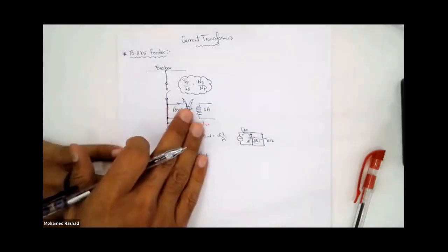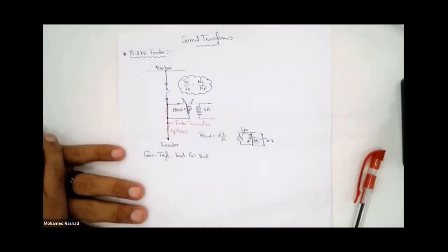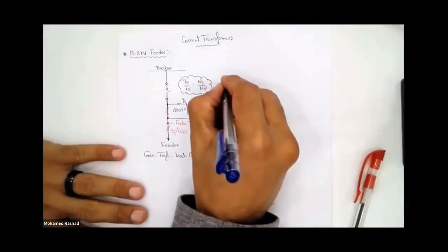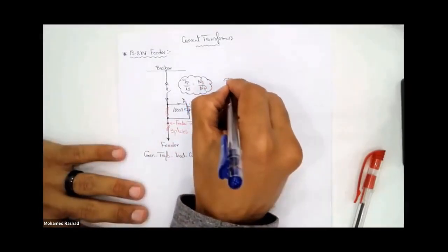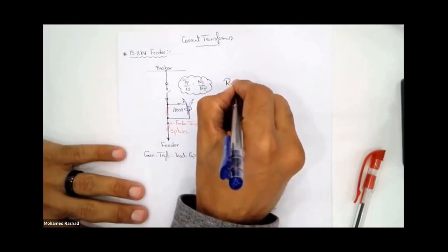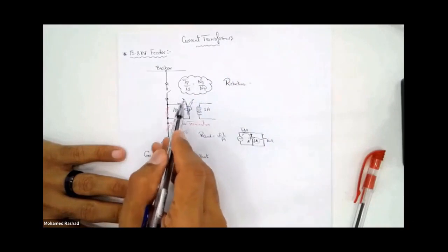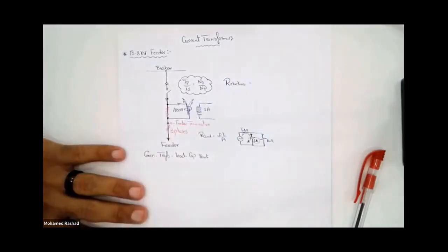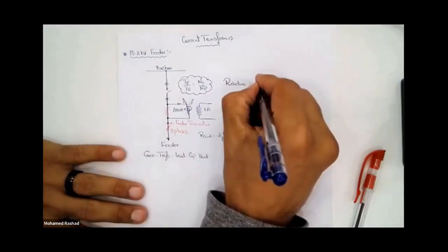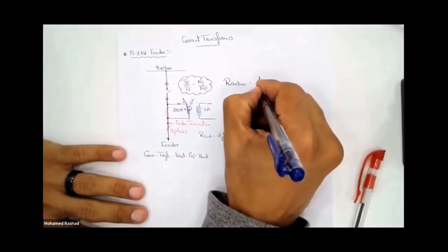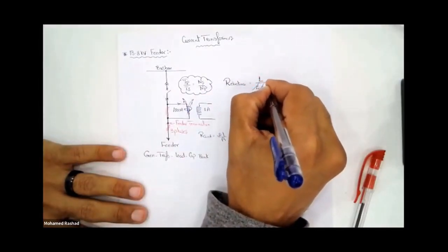The same exact concept applies to the flux lines you have. Your magnetic field also has a law that controls it, which is also called R. But here, this R is the reluctance. This reluctance is the resistance to the flow of my magnetic field or the magnetic flux lines, and it equals L over mu naught times mu R times the area.